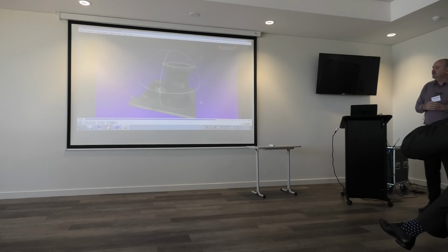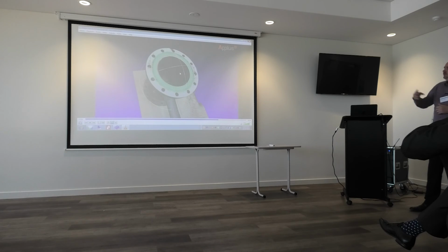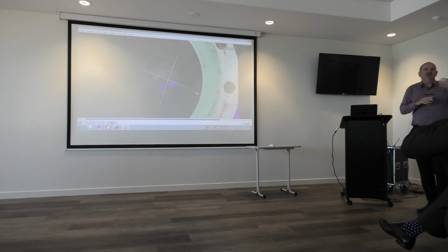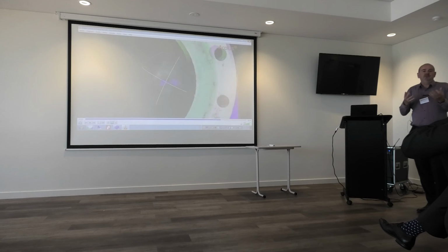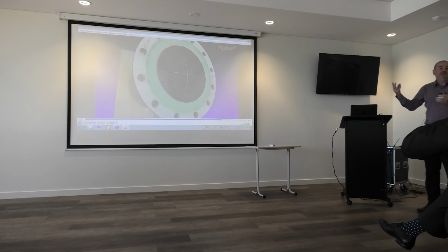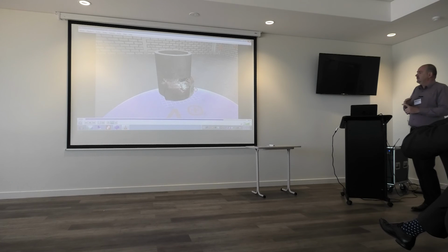So we get a pipe spill that's come in from a corrosion problem. We can actually do the same thing. We can do photogrammetry on that, and it allows us to create a model in 3D space. We can zoom that around, we can look at different details. So that in itself is actually quite useful to give to a client, but it actually lacks a little bit of information, because we want to actually attach to that other things that we've actually done, like chemical analysis, or there may be some spectroscopy we do with the SEM or something.